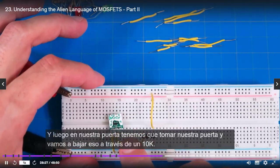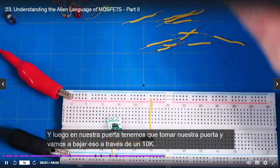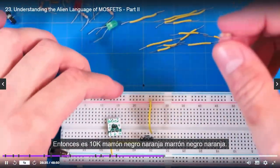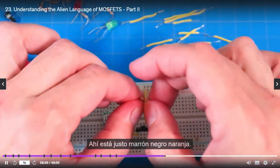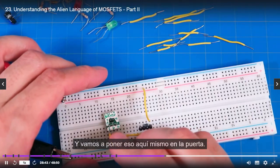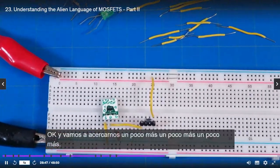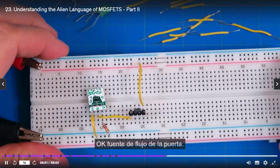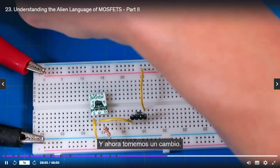Then on our gate, we are going to pull that down low through a 10K. What's 10K? Brown, black, orange. There it is right there, brown, black, orange. We're going to put that right here to the gate. Let's zoom in a little bit more. So you can see that's into the gate. Source, drain, gate.